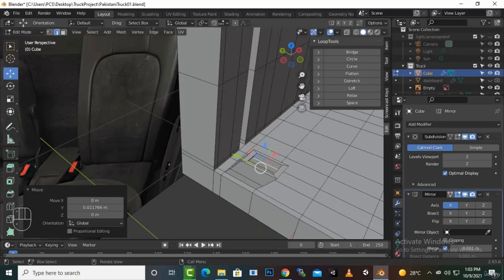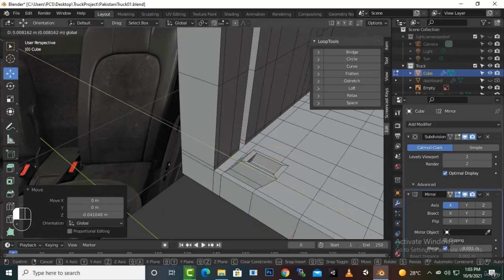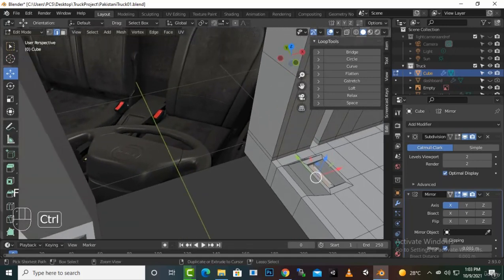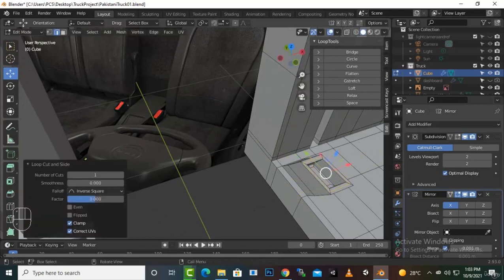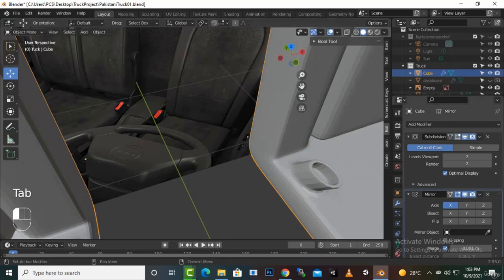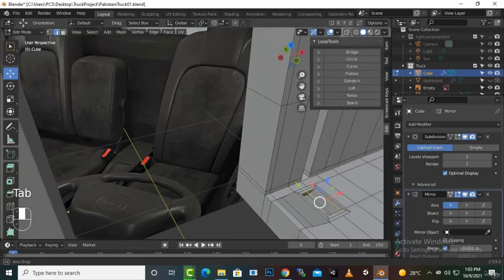to inner extrusion, a little bit more, and we will press E S again and F again, okay. Now we will add a loop here, and actually at this point we can create a loop, this one, okay, and this loop as well. These are very important. And now if we apply the subdivision surface, you can see the result, which is not very good because of certain problems.